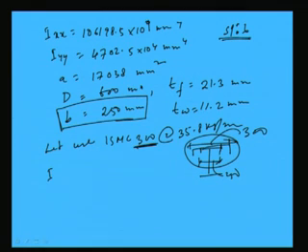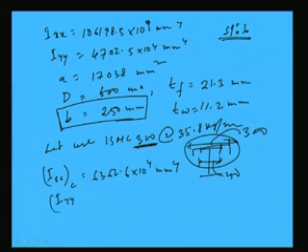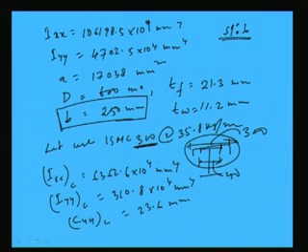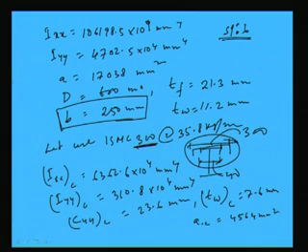So, from this again we can find out Ixx for the channel section, that will be 6362.6 into 10 to the 4 millimeter to the 4. This is given, right. Similarly, Iyy of the channel is given 310.8 into 10 to the 4 millimeter to the 4, and Cyy for the channel is given 23.6 mm, thickness of web of the channel is given 7.6 mm, and area of the channel is given 4564 millimeter square. So, these are the values given in SP6 which we need for the calculation of the combined properties, right.